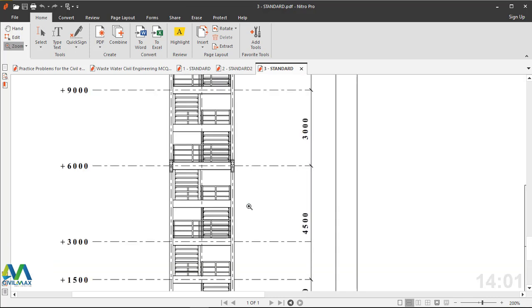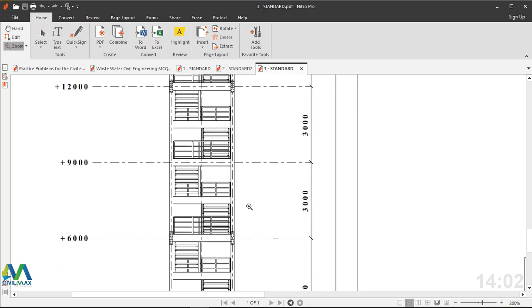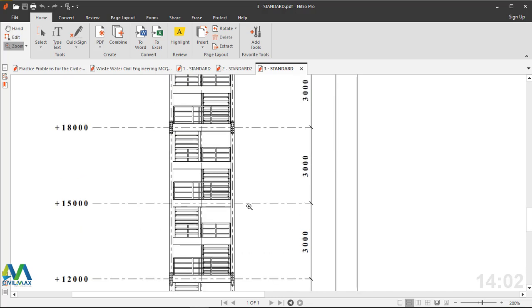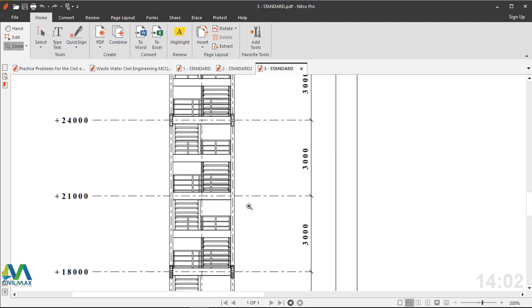Remember, creating elevations is very simple. Just go to drawings and reports, then create drawings, then come to GA. GA will prompt you with so many options of grid lines, and you pick from any grid line or plan view. The drawing will be generated for you. If you need general arrangement drawings and you intend to put dimensions manually, next time I'll take you a step to assembly drawings. Generating assembly drawings from a model with lots of steel structures will normally take time to load, and we are considering time. That one I'll show you in the next presentation.